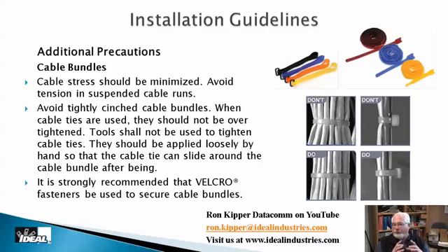We used to like to make really nice tight bundles out of these cables and make that bundle look really neat. And they're finding out with Cat 6A, as I mentioned earlier, with alien crosstalk being one more thing we're looking at, they're telling you not to bundle them so tight. Depending on the cable, how you handle that wire management is kind of up to the particular job. And again, if you're putting cable ties up in a drop ceiling or something like that, you probably ought to be using plenum rated cable ties to do that.